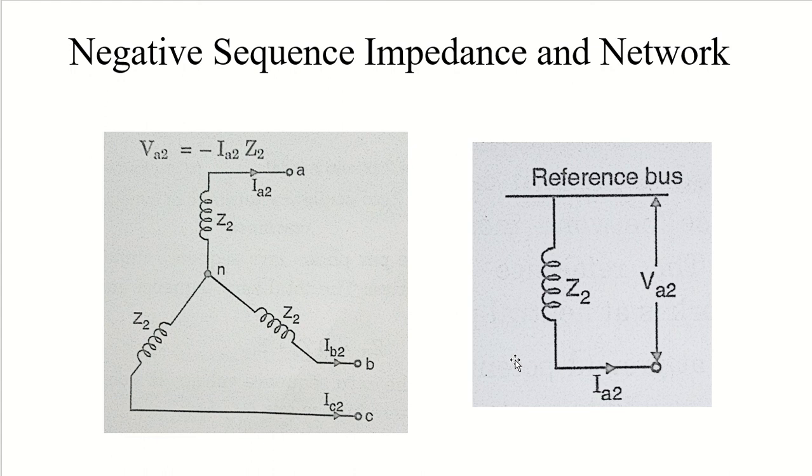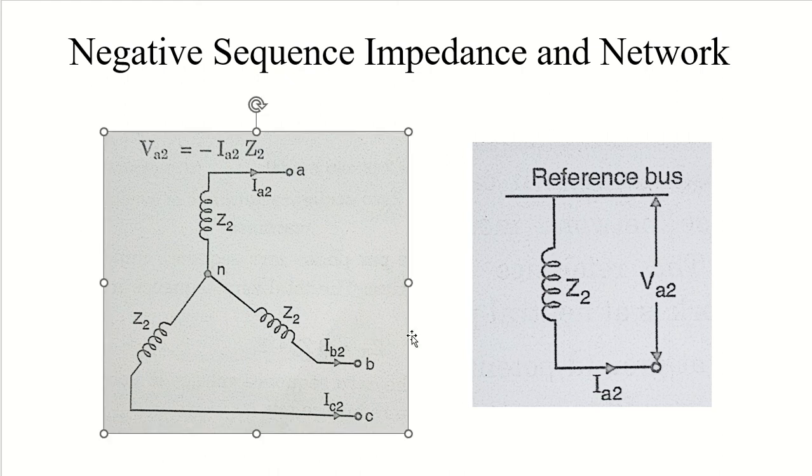So these two axes I talked about, D and Q, are the conversion from ABC into the DQ model of my machine, which is a representation of my three phase into two phase for simplicity in the calculation. So this three phase negative sequence model and one phase model of the synchronous machine, you can see here in this image, both of them.